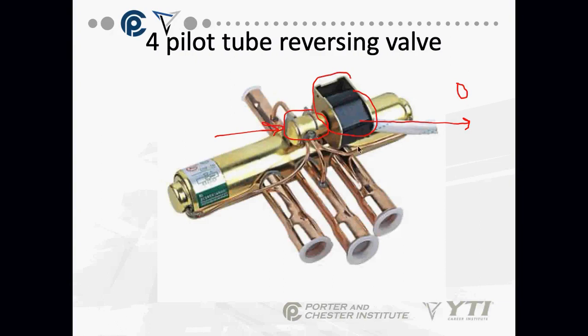You have to really protect this whole assembly against getting overheated. So you're putting very hot flame on all four components of this, and you're also having to protect this against getting overheated. Copper and brass conduct heat very well. That's why reversing valve changeouts are so nasty to do. It's because you've got to braze in a very close, confined area and control heat.